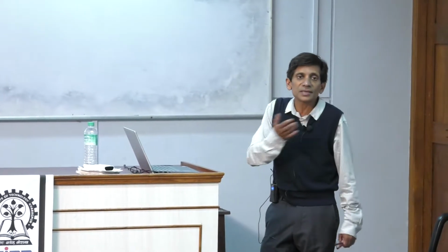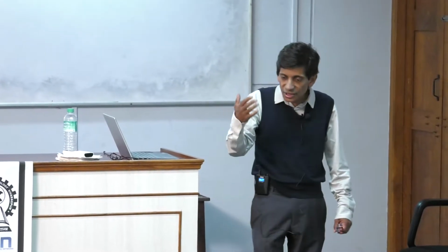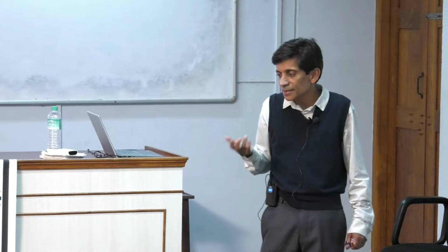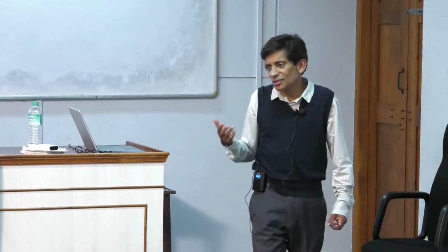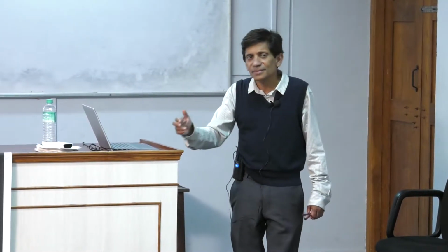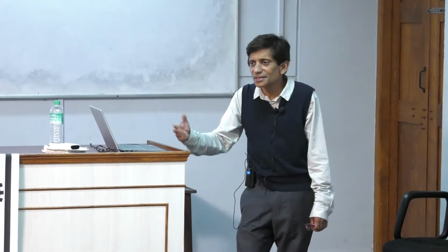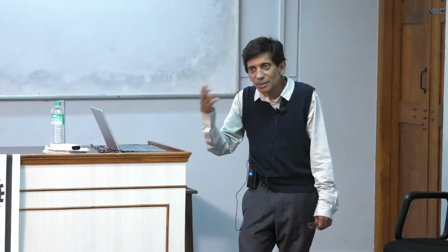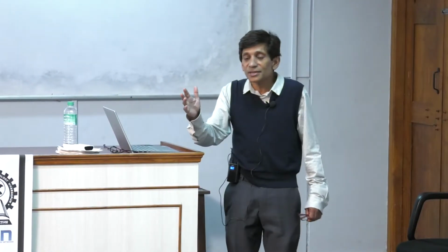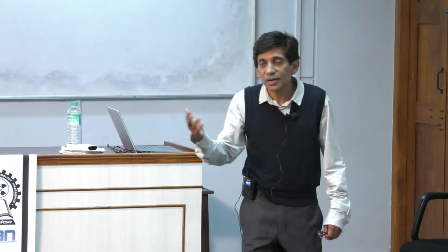So if I'm going to do a BSA filtration, I want to reject BSA, for example. BSA molecular weight is around 70 kilodalton, something like this. So if I use a nominal molecular weight cutoff of about 60 kilodalton, I'm expecting to get a reasonable rejection. But looking at different 60 kilodalton membranes, I might find different rejections. So one might give me 85%, one might give 95%, it depends.